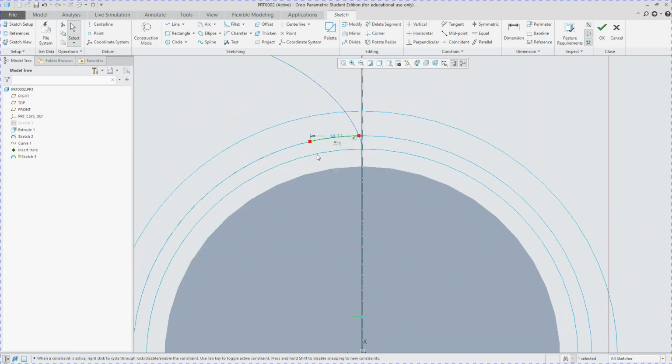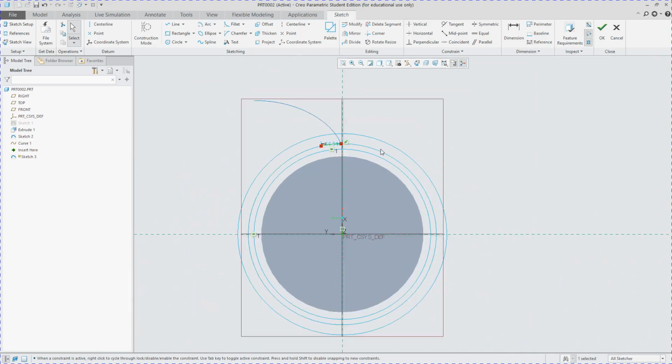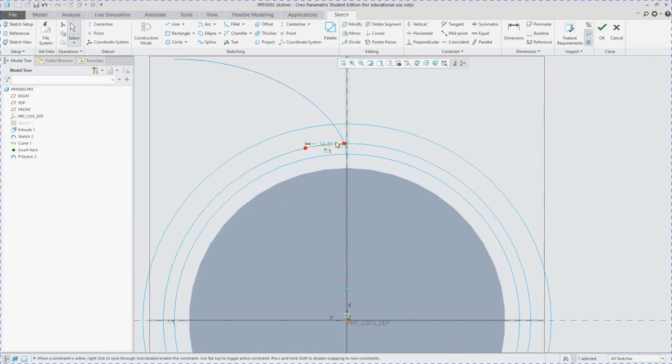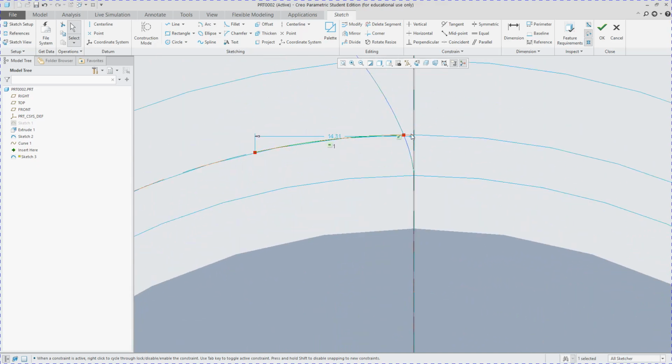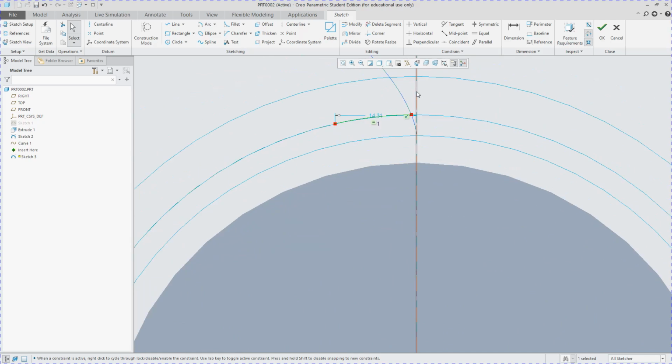Then we're going to just make an arc of some length, because we know what the tooth thickness is in the relations, but the tooth thickness is defined as an arc length, not a straight line distance, which is what we've got right now. We've got the distance from this plane to the end here.